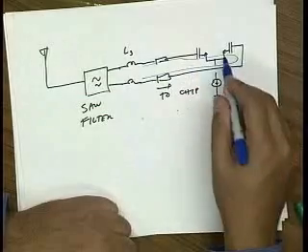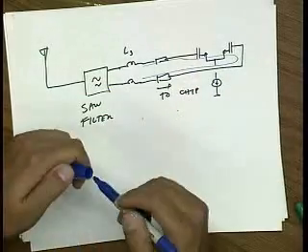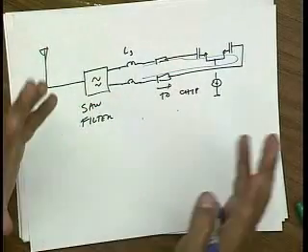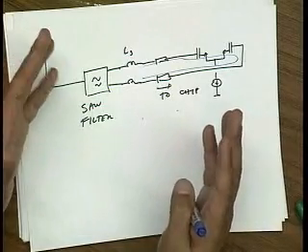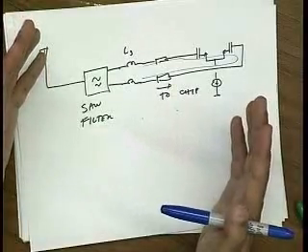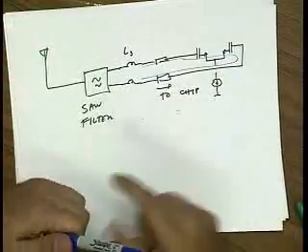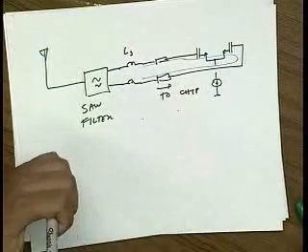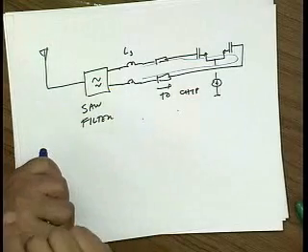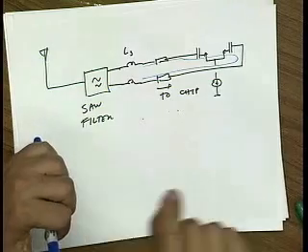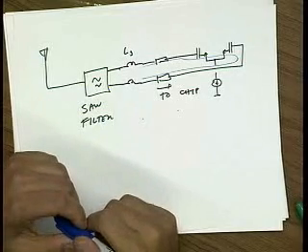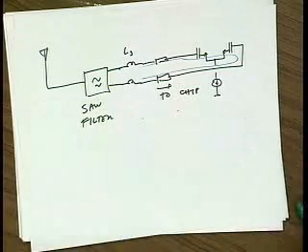On the other hand, ground is a little bit scary because lots of things are grounded, right? All the transistors, their bodies may be grounded. You might have multiple ground pins on a package. So if you're not careful, your ground current may take a path that's very different than you intended. So in the case of a single-ended design, if you know what you're doing, you will carefully ground the input stage separately from everything else and make sure you control that path. But if you're not careful and you share that ground, you actually don't even know what path the return current is going to take. Okay, so that's the advantage of going differential.